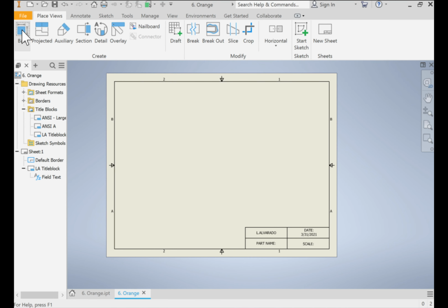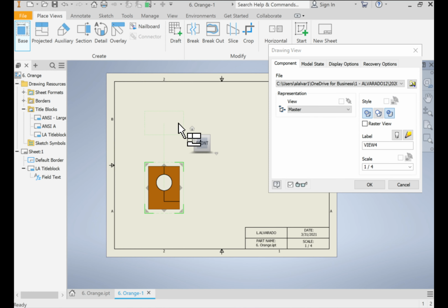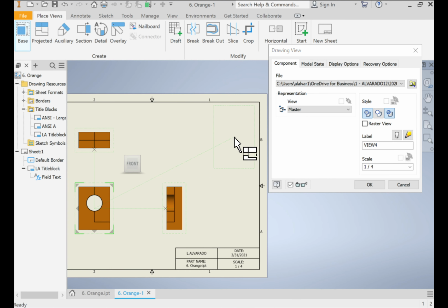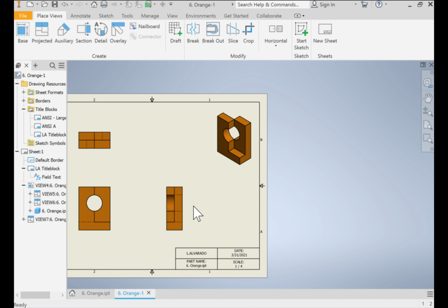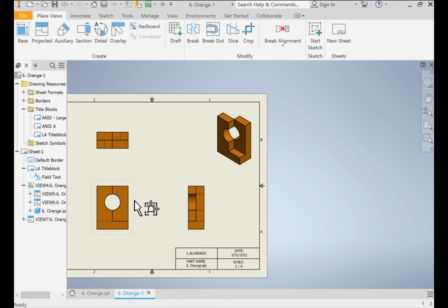Now we can go ahead and start dimensioning everything. So you're going to need a front view, a top view, and a right side view, and if you have the space, which you should, an isometric. Okay, and make sure that you give yourself plenty of space as you are working on this.